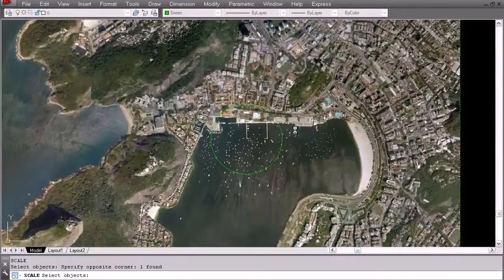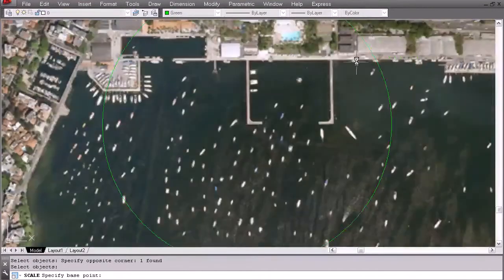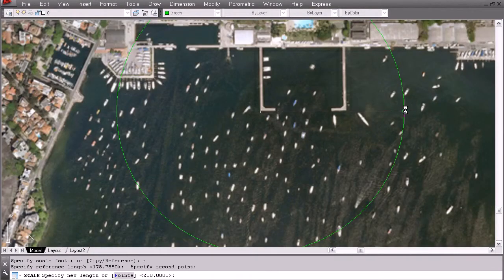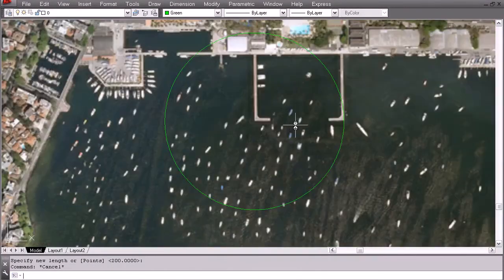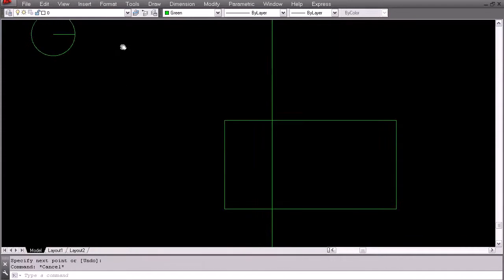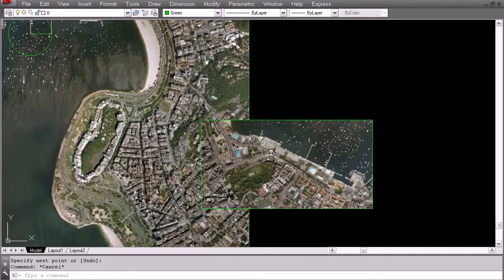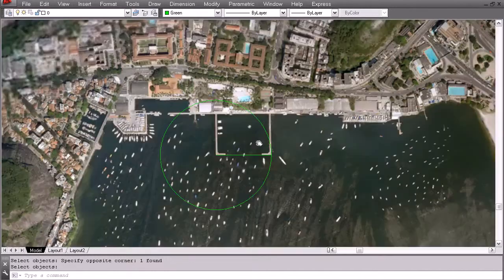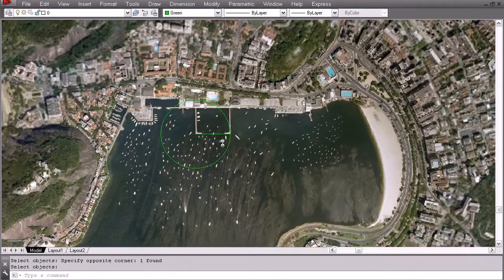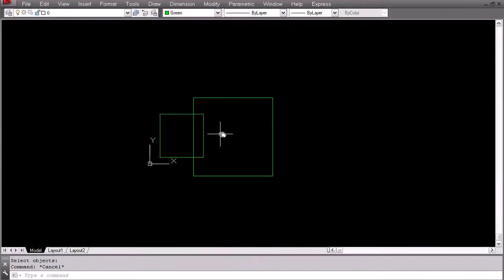And using the scale tool, I will scale from the middle of the circle, snap onto it, using that reference. And I'll grab this corner here, and I will just scale it to be there. So this should more or less, and I do again say more or less, be the right scale from point to point, which is the same as what we measured being here. Again, if you have Google Earth running, then all you have to do is measure two distant points as far as possible from each other, clear points if you can, and get those 2 points scaled up correctly on your drawing. Once I delete that, I know that this image is at the right scale.